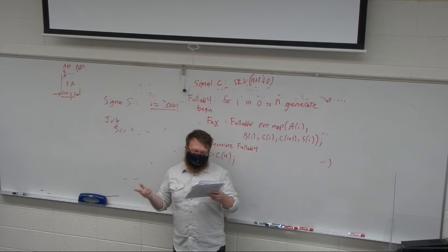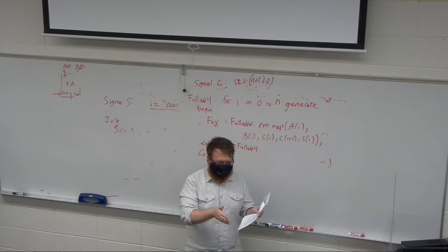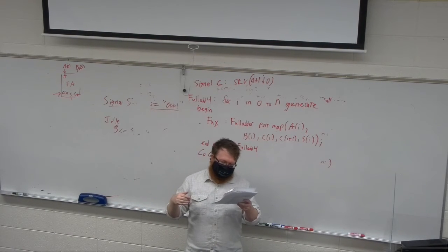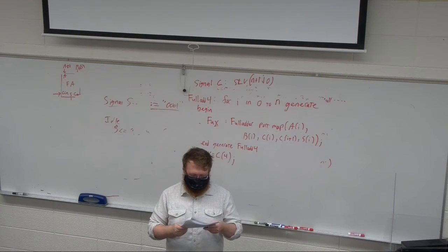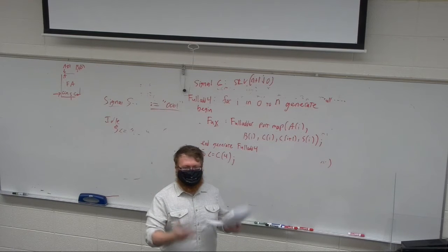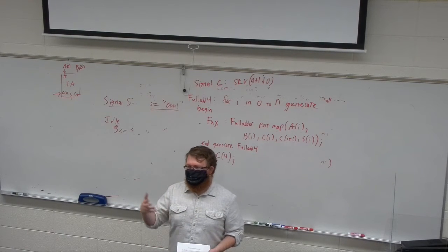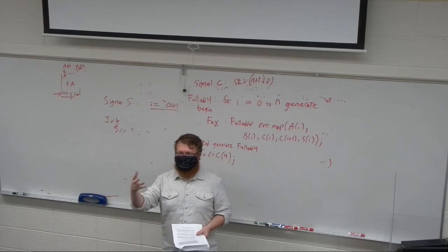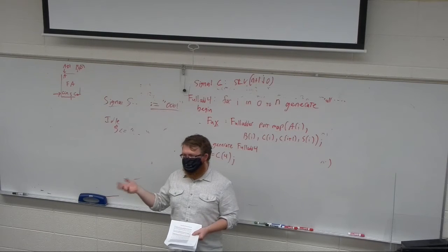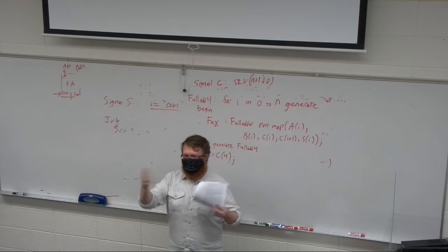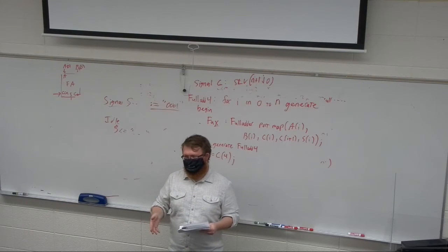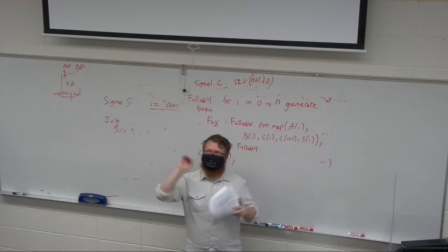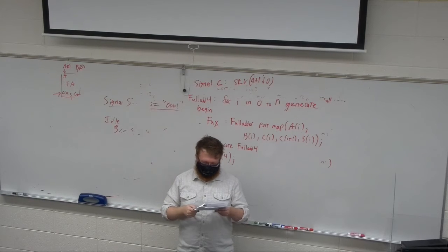You can do base plus offset, so you have an assumption and then you just define the offset. You have indirect addressing and a bunch of other ones, but we'll not worry too much about those. The next one is it uses a large number of registers and has a few processes that will access memory. In some computing architectures, you'll be pulling stuff in and out of memory all the time, but memory is slow compared to registers. So it uses lots of registers and only writes to memory when it has to.